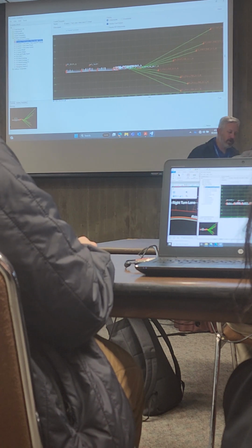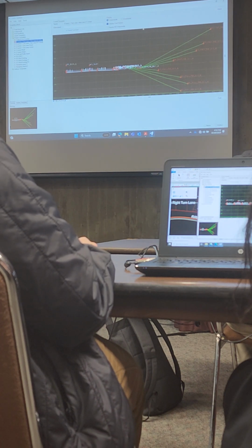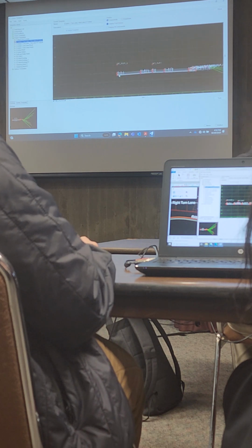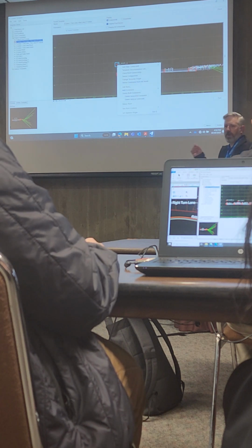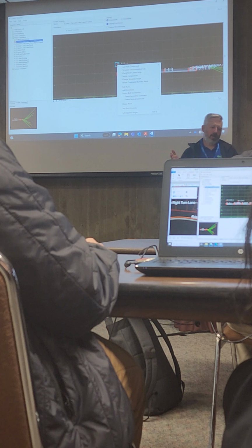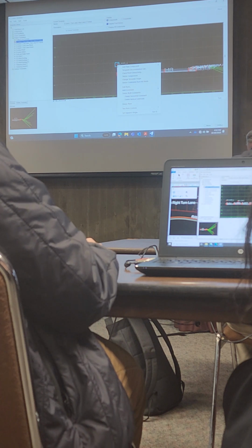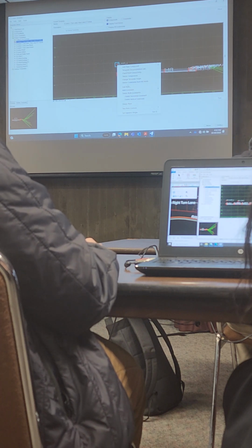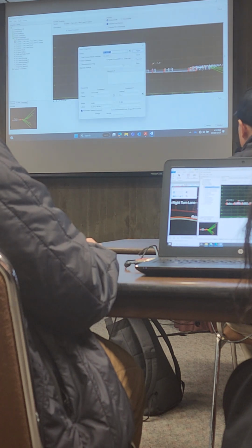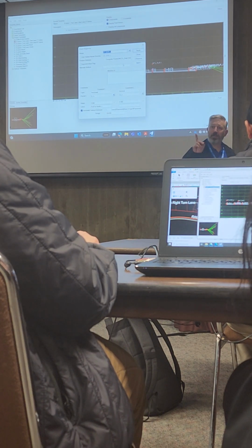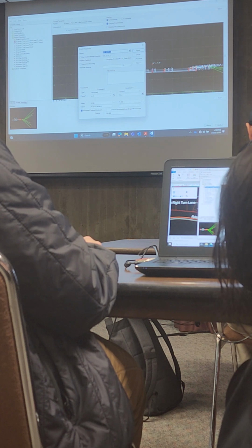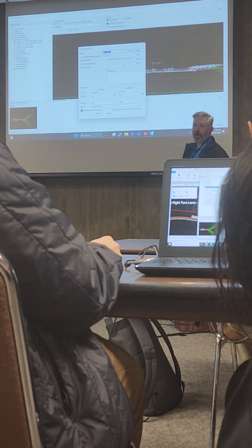I can edit this template, and what this template's going to do for me is allow me to make some adjustments. And I'm just going to quickly show you what it does. This little point, remember we talked about those quarter references and all that type of stuff, right? You can set this up. We'll go ahead and I'm going to edit that so I can look at some properties. What we did was we said, look, if somebody draws something on that symbology, and then we set it as a quarter reference, that point needs to go hunt for that line in the file.